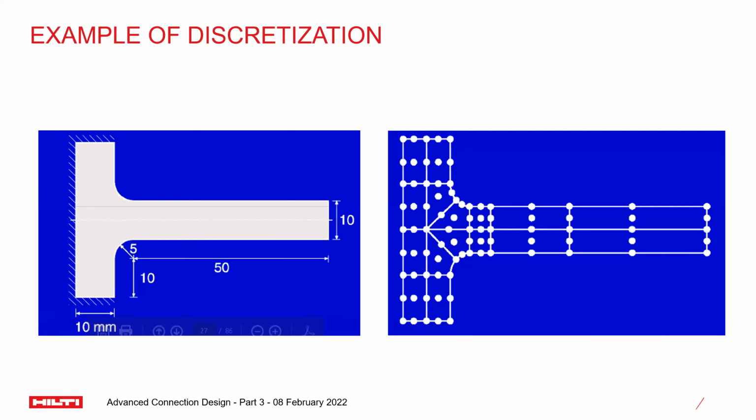So in this 2D example, the 2D plate or shell elements are used. It should be noted that there is a larger concentration of elements where the curvature is changing. So 4 nodes are used on the longer and straighter sides, whereas triangular elements are used at the change in curvature. This is a commonly used technique to capture the correct load transfer that goes through this curve.